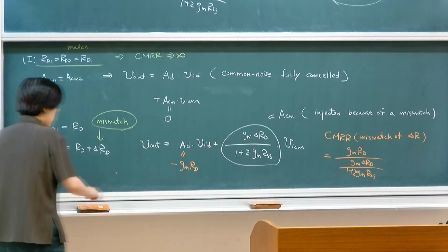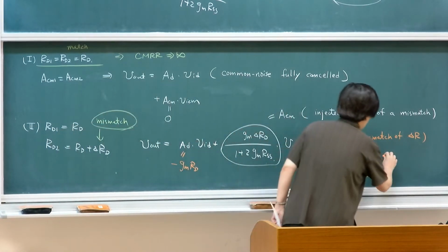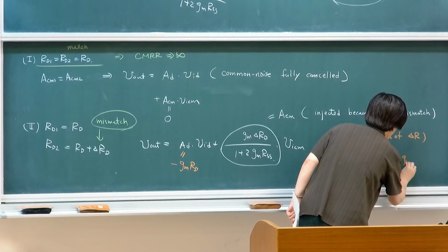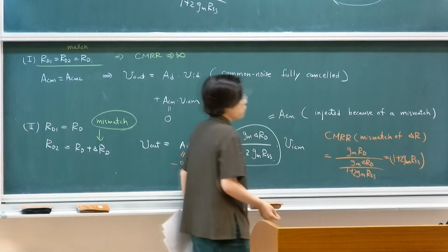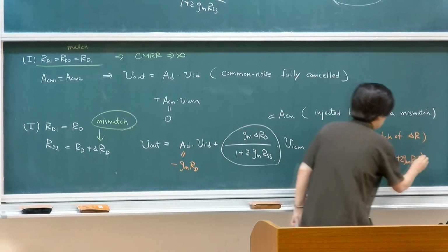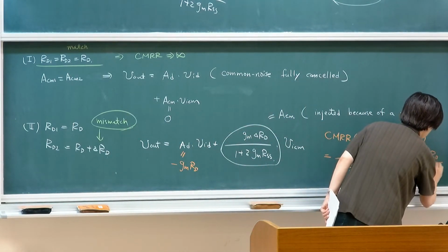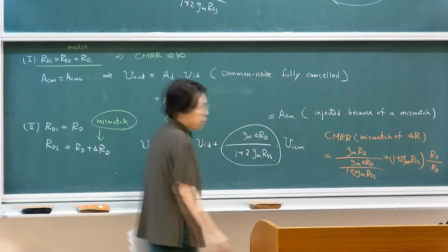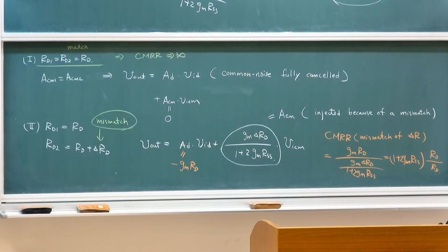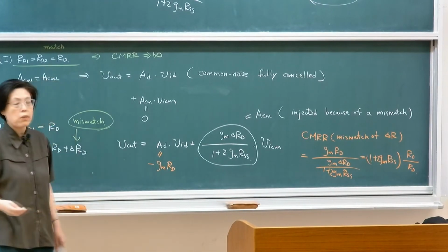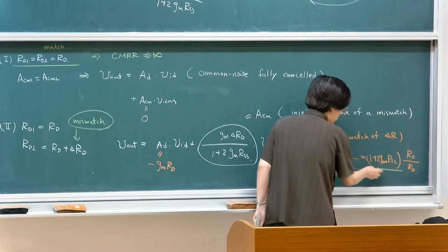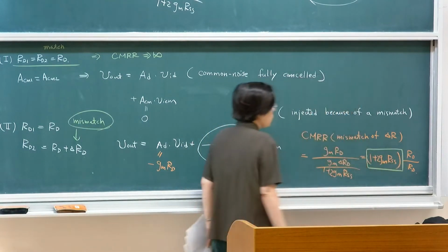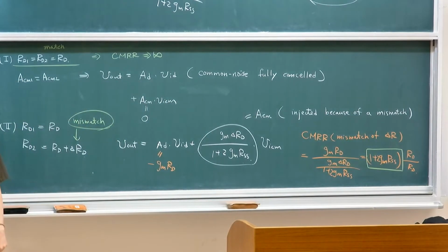Okay? So if you rearrange it, this is the attenuation factor from the degenerate current source. So to improve your overall common mode rejection ratio, even in a fully differential architecture, what you need to do is still the same. You still want to improve your current source, or the suppression of common mode gain.